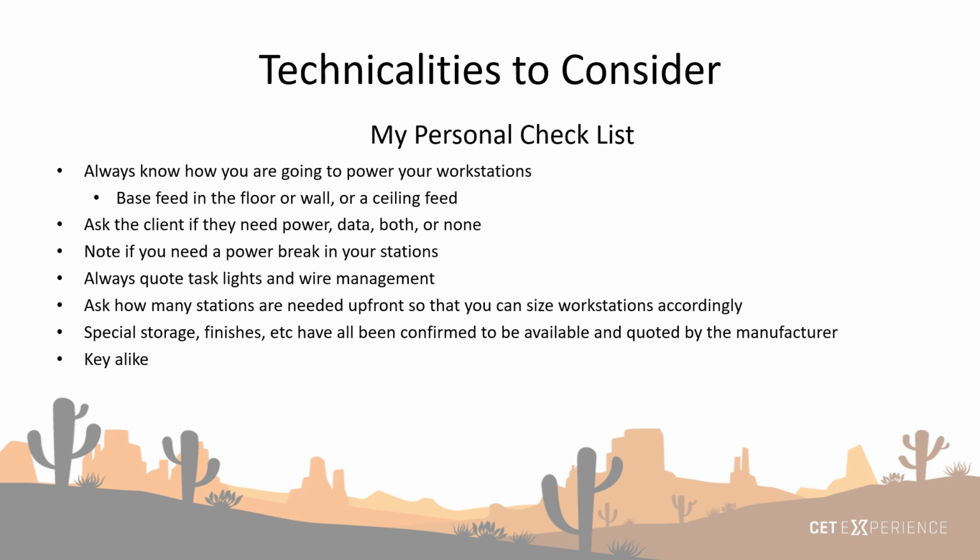Technicalities to consider when designing with your panels. This is my personal checklist. This is what I like to run off of whenever I do anything for panel-based designs. Always know how you are going to get power to your workstations: base feed in the floor or wall, or a ceiling feed. Always ask the client if they need power, data, both, or none.